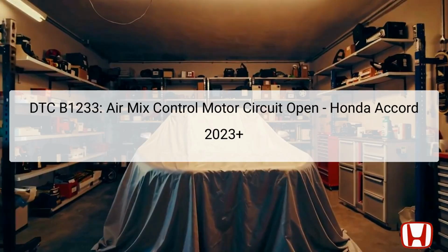The Diagnostic Trouble Code, DTC B1233, indicates an open in the air mix control motor circuit, specifically related to the driver's side in Honda Accord models from 2023 and onwards. This error occurs when the air mix control system detects that the input voltage from the air mix control motor exceeds the specified limits, prompting the climate control unit to flag this abnormality.